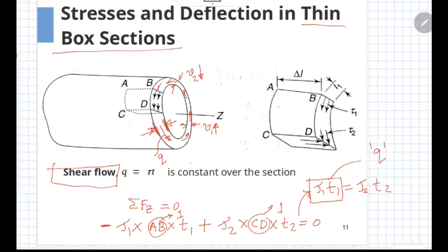Now you can see the analogy between the flow rate and the shear flow, and the velocity and the shear stress. So in this case, the shear flow indicates the analogous fluid flow through this channel, and the stress at any point in this cross section is the velocity of the analogous fluid passing through this cross section.